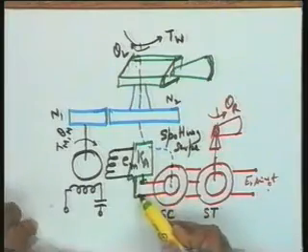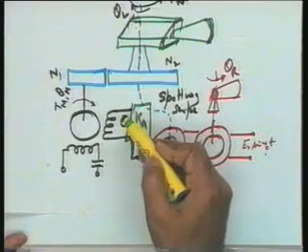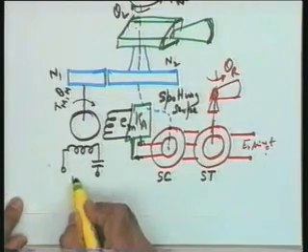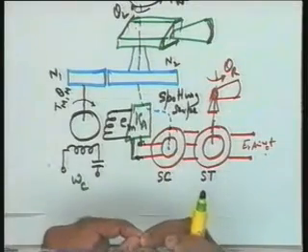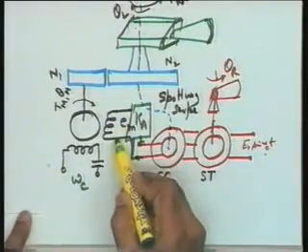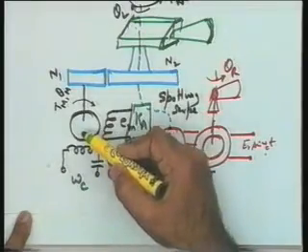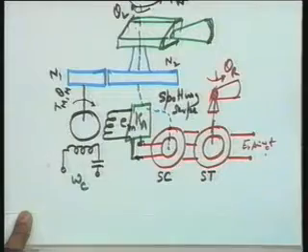Now this modulated signal is being amplified by an AC amplifier, and the output is a modulated signal again. The frequency in the reference here also should be the same omega_c for the two devices to be compatible. So this modulated signal is being fed to the control phase, and this control motor is producing a torque and hence a position theta_m, which is again a DC signal.